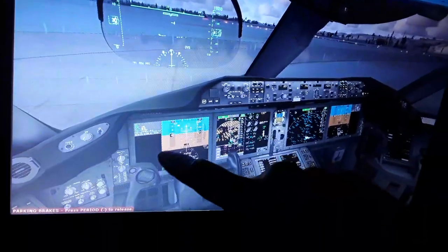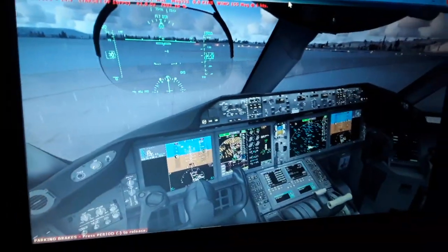It is the position where this also calculates the center of pressure, and also the stall. At the top surface of the wings, the airflow will become detached, and the aircraft is going to start stalling in the air. So we need to avoid the stall speed all the time by monitoring the primary flight display, the airspeed indicator here. You can see where the stall speed is displayed with a yellow and red line. So our airspeed during the whole flight is gonna be more than the stall speed as much as possible.